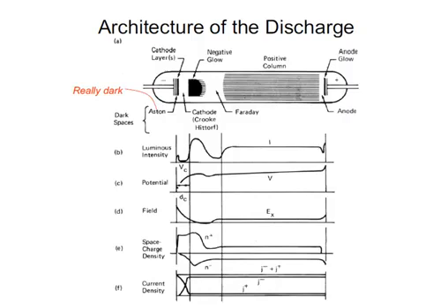And usually when we use a DC sputtering or PECVD power supply, the applied voltage is around a few hundred volts. So the cathode is negatively biased, and usually the anode is grounded, so the potential is 0 volt.